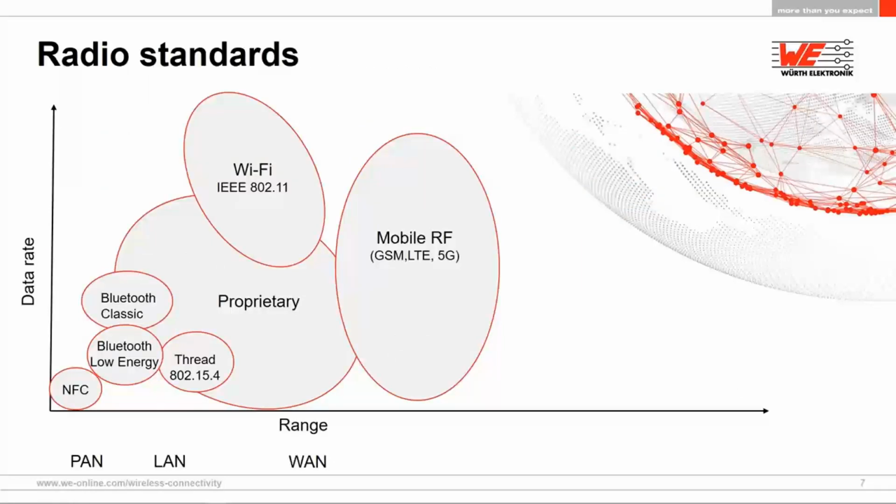Yeah, I mentioned radio protocols. There are a number of protocols on the market. Probably very popular and well known is Bluetooth. Bluetooth Classic, the older, Bluetooth on 2.4 gigahertz. Bluetooth Low Energy, as from 4.2 onwards, we run 5.1 on our Bluetooth Low Energy modules. Then also Zigbee and Thread and so on.